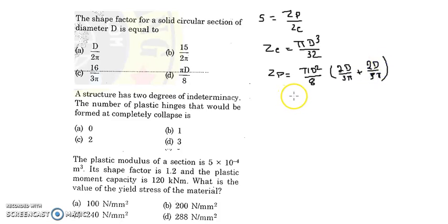If you are not getting it, if I draw a circle, this is where my neutral axis is, and this is the center distance yc bar, and this is the center distance yt bar. You're supposed to be master of all these things. Practice is the key. Yc bar and yt bar are each 4r by 3 pi, and we know 2r equals d.